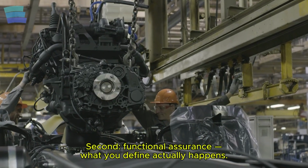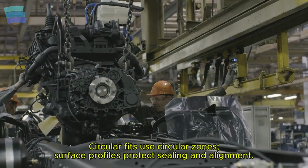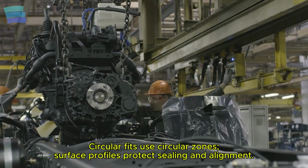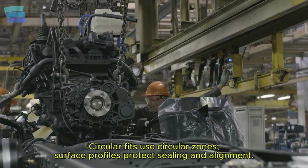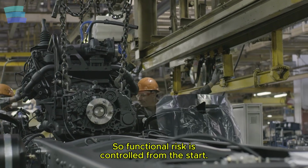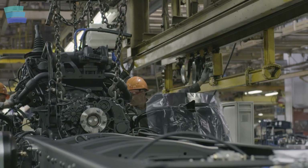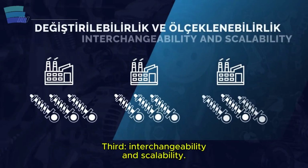Functional assurance. What you define on the drawing is what actually happens in assembly and in the field. Where circular fit is needed, you define a circular tolerance zone. Where surface integrity is critical, you use a surface profile control. Functional risks are brought under control from the very beginning.